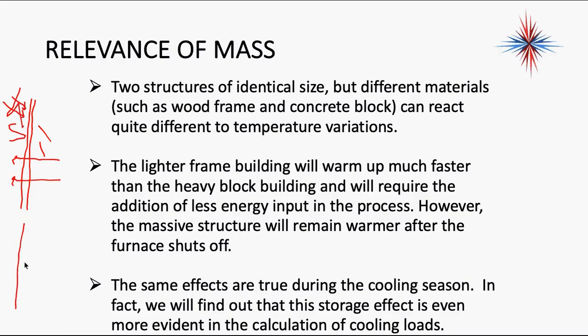If I take a concrete block wall that's thick, 6 to 8 inches thick of heavy stone, the heat's going to take more time to warm up this wall before heat starts moving through. Okay, there's a delayed reaction. In other words, if the sun starts hitting the south-facing wall around 1 o'clock in the afternoon, that sun will not warm that wall enough to start heating my inside environment till maybe 3 o'clock in the afternoon.